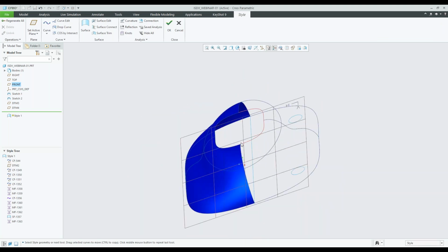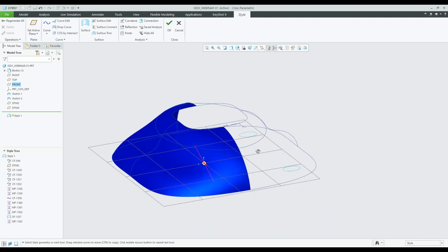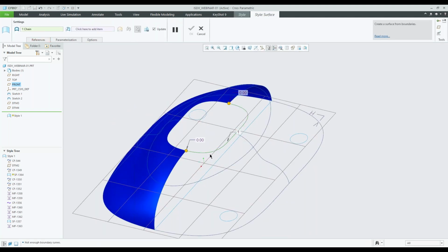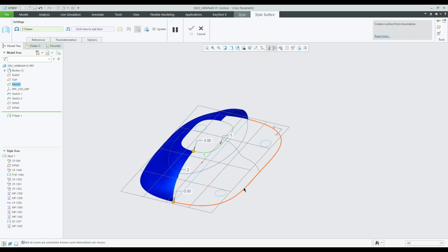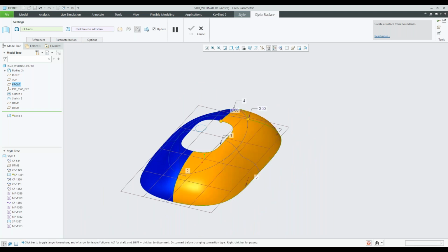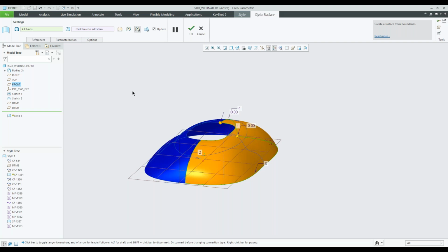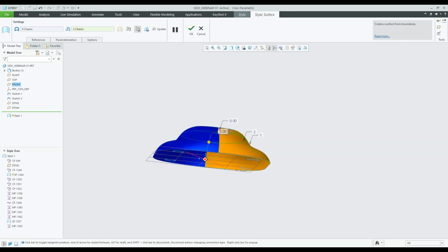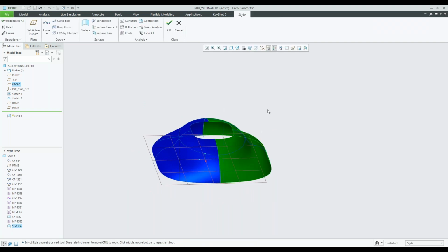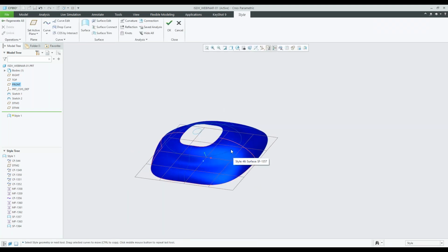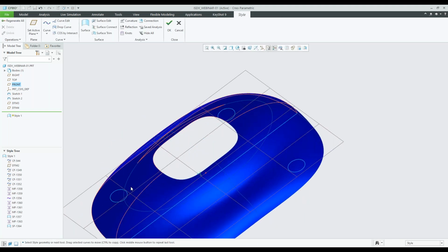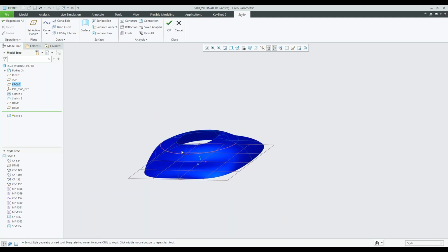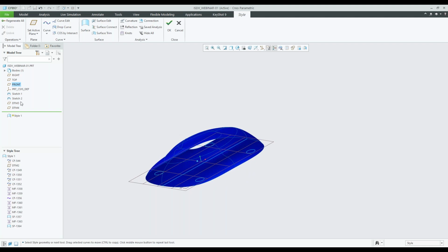We'll just go ahead and create a surface. So let's go to surface up here. We'll grab that curve, hold Control, and then once again go to internal curve collector and grab this curve and that curve, and there it is. We also had these circle sketches to create holes in the surface, and that was actually created on Sketch 2.